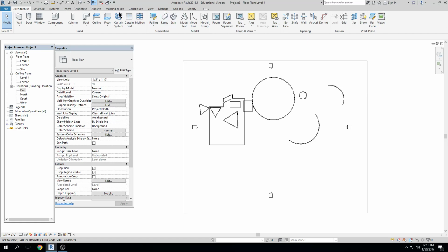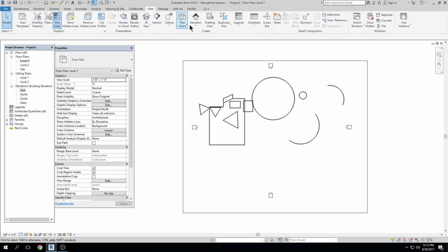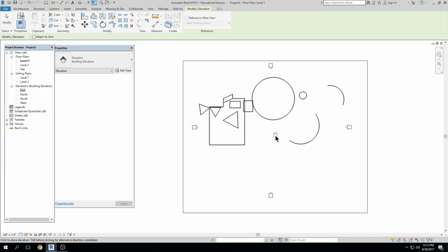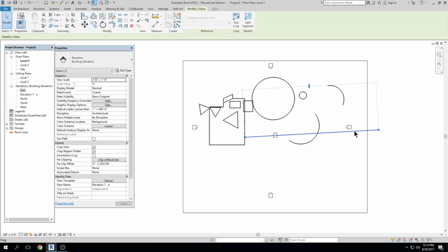Let me show you something else here. All right, so here's my elevation. This is just going to go to the extent. So with these exterior elevation markers, I'm seeing a portion of this. We're seeing everything here, right? With this marker that I made, I am allowed to alter it. You see how I have these grips that allow me to choose the depth of it? Essentially, anything within the boundary of this line will be shown here in your elevation.